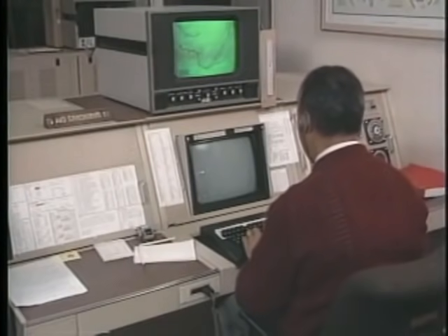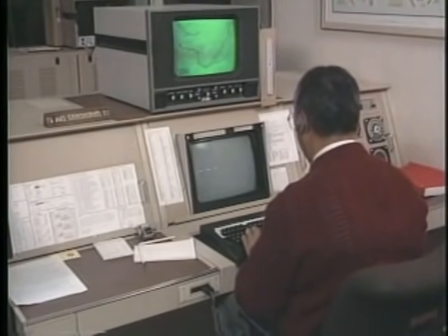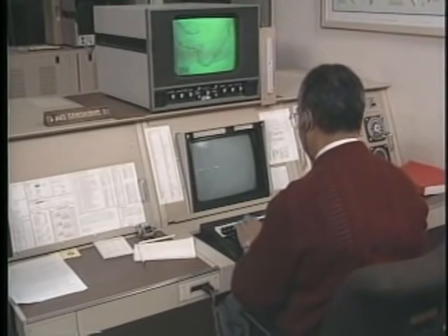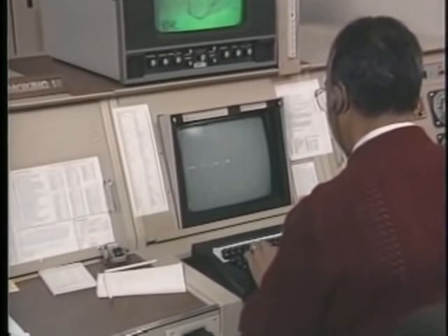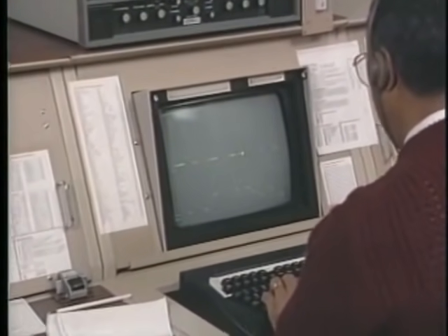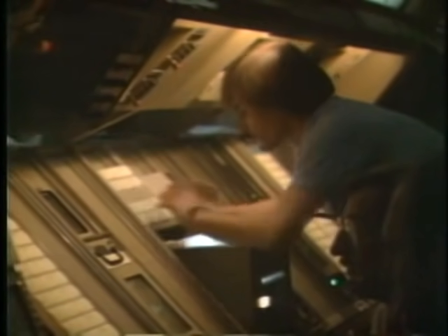When you file your flight plan, the procedures for achieving IFR traffic separation for your flight are set into motion. The FSS specialist forwards your flight plan to the ARTCC facility from which your flight will originate. There, it is processed and the selected route of flight is approved or amended as necessary. Then, when you depart, your flight information is relayed by computer to the various centers you will be going through.